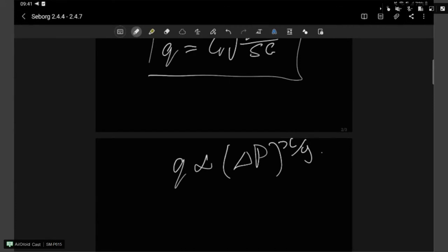So for a valve, let's say we are using a Cobra, really well made garden tap, that CV value is 10. If we use a Chinese one that is very similar, it looks exactly the same, but the internals are slightly less, say it's more rough on the inside or something like that, that CV value will change, even though the thing looks exactly the same, because of the wall friction and those sort of things that change in the specific valve.